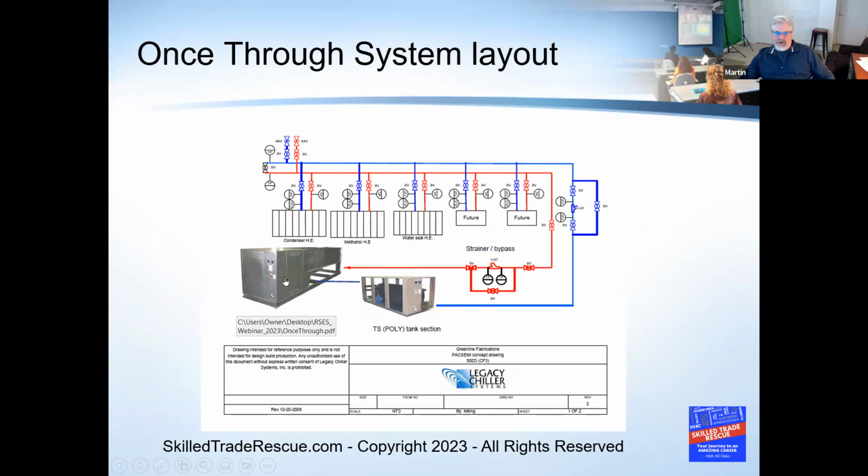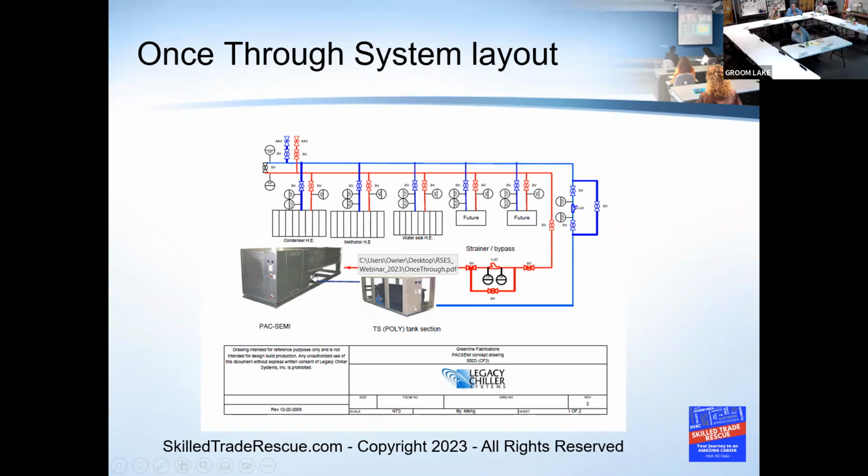And when you gauge up on it, look on the readouts, it's running normal pressures when you're there, even on a hot day. The way this will happen is a customer makes some kind of a change. I can't tell you how many times this happened. Let's say on this condenser or methanol heat exchanger, someone downstream opened up a valve and dumped a crap ton of heat into this one heat exchanger, which immediately hits that evaporator. What happens to your head pressure? Yep, goes up. So that's the kind of thing that will cause a problem for you, right?